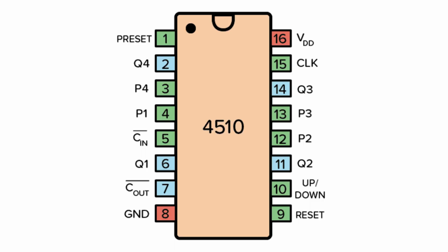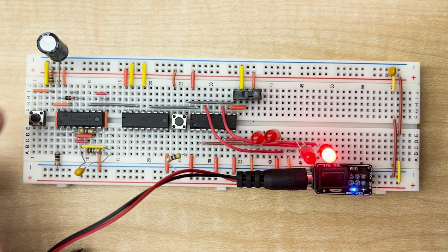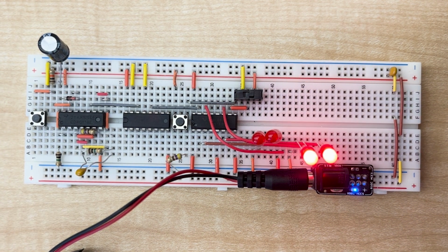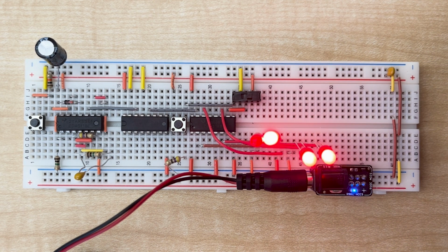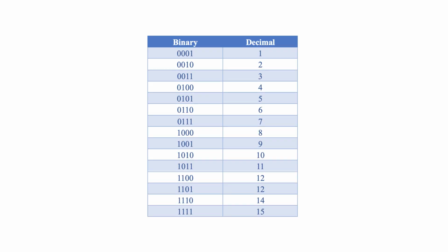The 4510 chip receives BCD data via input pins, where it is set to the initial count value and the sequence starting point. The chip internally processes the input and increases the count, using logic circuits to read and advance the count in BCD format. The chip's outputs, which are shown on pins Q0, Q1, Q2, and Q3, show the binary coded decimal count, with each pin correlating to a distinct bit and making the final count number.